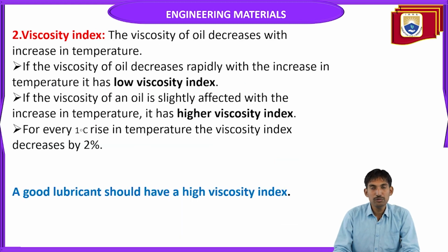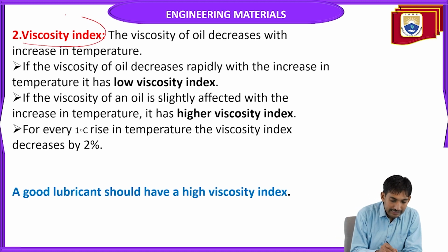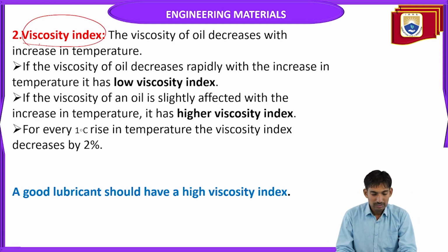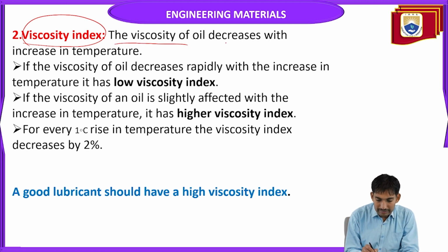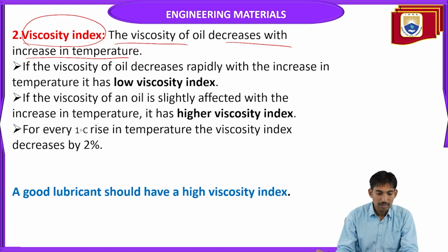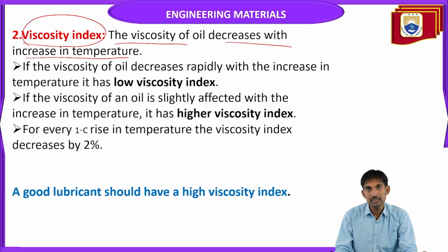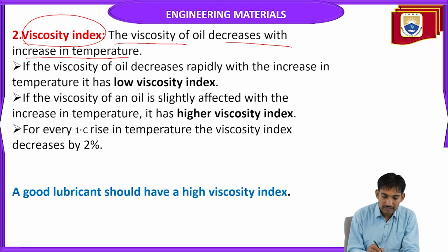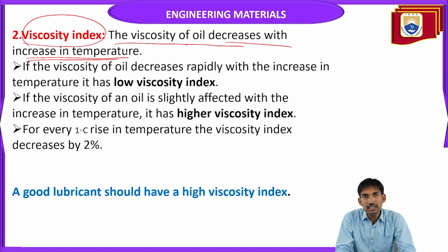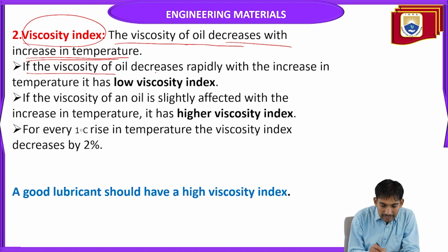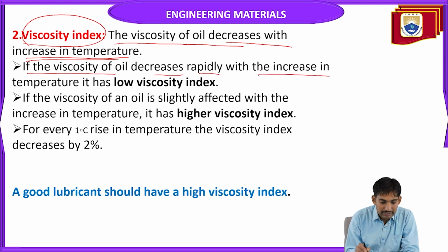The second property of the lubricant is viscosity index. The viscosity of oil decreases with increasing temperature. What happens if you heat the lubricant oil? The viscosity of oil decreases with increasing temperature. If the viscosity of the oil decreases rapidly with increasing temperature, it has low viscosity index.